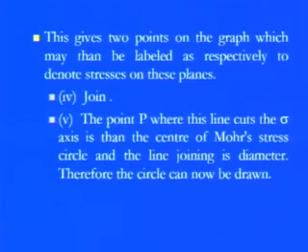The next slide presents those combinations and how, including them, we can draw the Mohr circle diagram. Here we get two points on a graph, represented by the stresses on these particular planes. First, you have sigma x and sigma y on the x-axis, so you need to label what the value of sigma x is, what the value of sigma y is, and what the combination is. Because we have two normal stress components, join those two on these planes. We have one plane that is the sigma plane, and the tau plane, where again we have to be careful whether this tau xy is positive, meaning above zero in the first quadrant, or negative, meaning in the fourth quadrant, on the lower side.